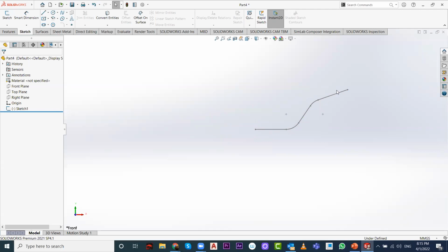Okay, so now I can't edit this sketch while it's in gray, locked right there, because I'm not now in the sketch interface. So I couldn't change any dimensions of any of those lines here. Why? Because I'm now in the feature interface. I can't see the exit sketch option right there. So if I double click here, or edit the sketch from there, now I'm in the sketch interface, so I can change or manipulate the values I want here.